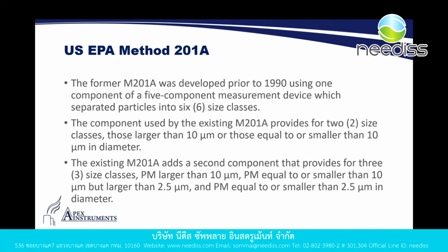I don't have an image of it in this presentation, but it's called a cascade impactor, where we can actually do particle sizing of 7 particles. The complexity of that particular device is that each of the 7 stages of capture vary the size of the PM captured in each stage depending on the individual source, the flow rate, and the calculations.